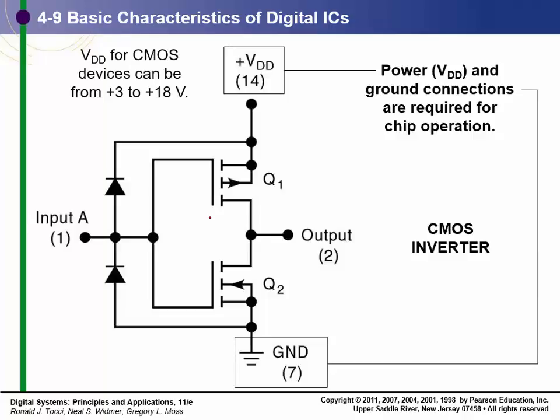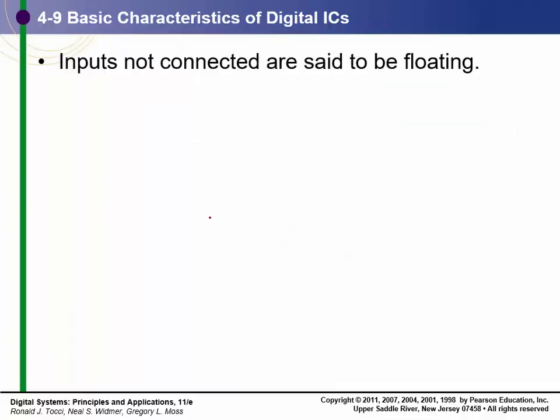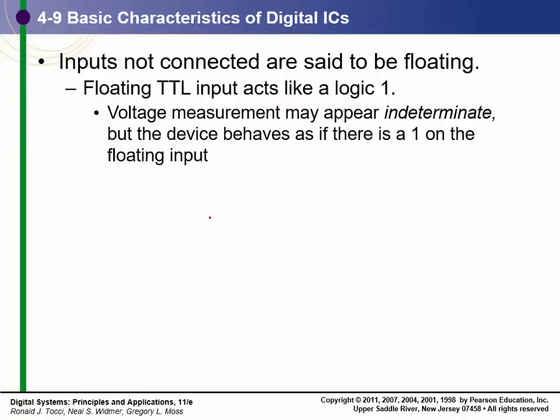Again, this is the circuit. Since you haven't had your course in electronics, I'm not going to go through this. Okay, let's go through some terminology that you do understand, or will understand here. Inputs that are not connected to anything are said to be floating. So in other words, if I leave an input unconnected, it's a floating input. Floating input typically will float high in TTL.